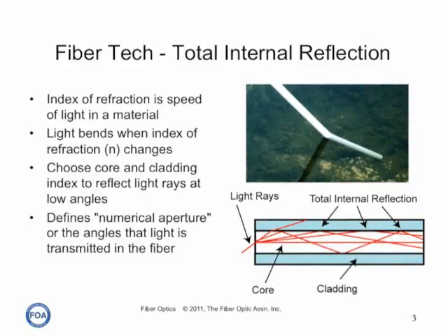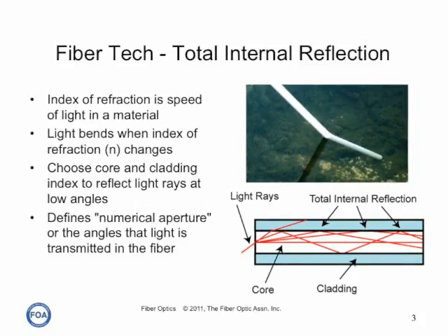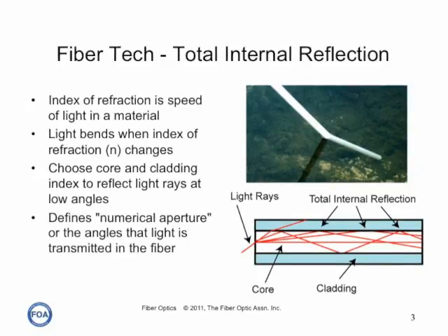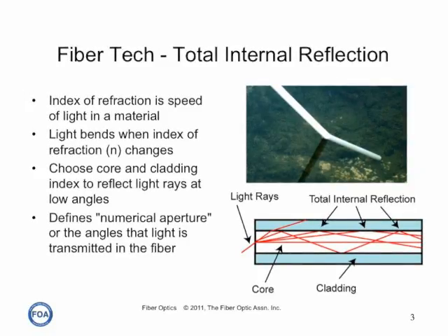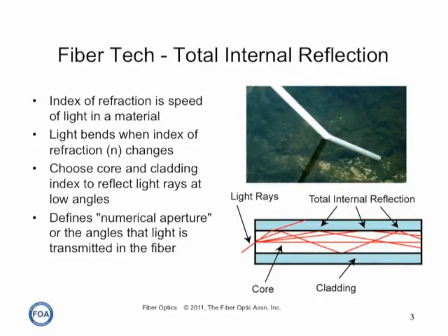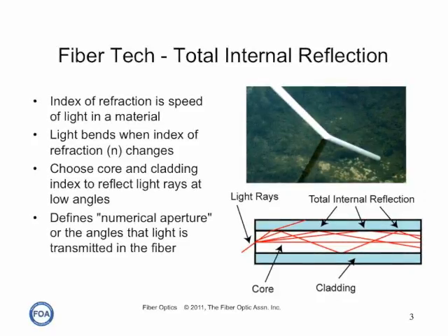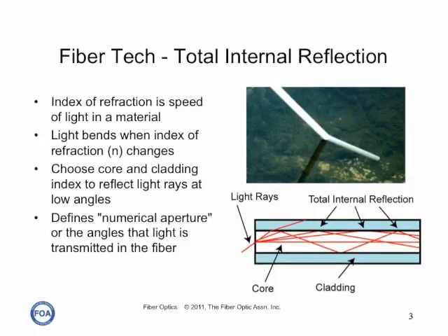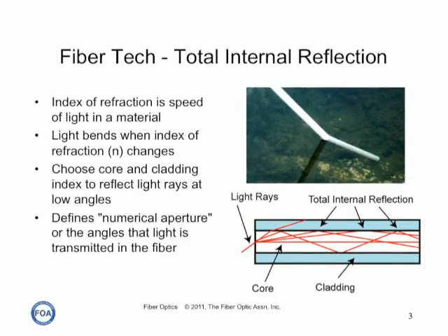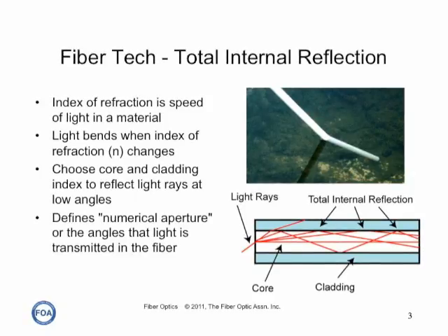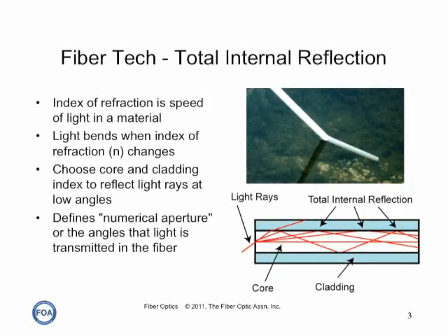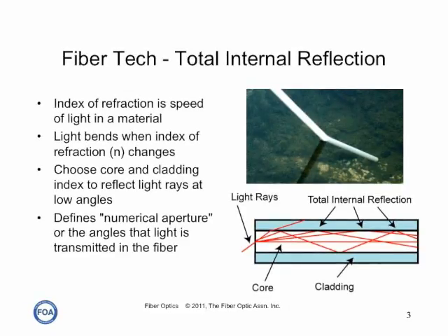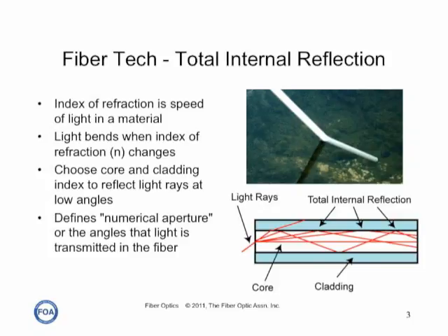You can see this on the diagram of a step index optical fiber that we show below. As the angle of the light becomes shallower and shallower, at some point all the light is trapped in the core. Well, we can take a step index fiber like that and a beam of laser light that's visible to us, and we can actually demonstrate this phenomenon. We're going to do it with a large core step index fiber.